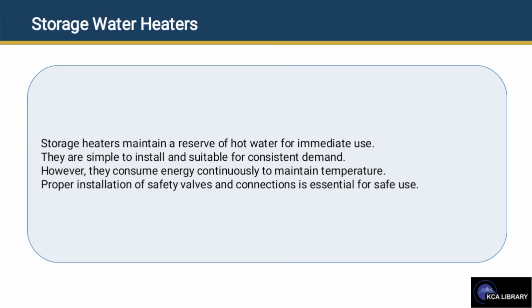Now, storage water heaters. Storage water heaters maintain a reserve of hot water for immediate use. They are simple to install and suitable for consistent demand. However, they consume energy continuously to maintain temperature. The proper installation of safety valves and connections is essential for safe use.